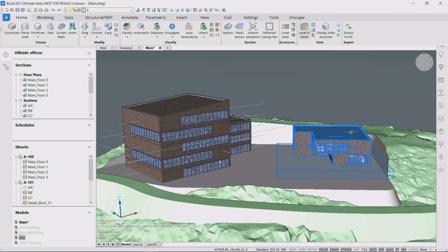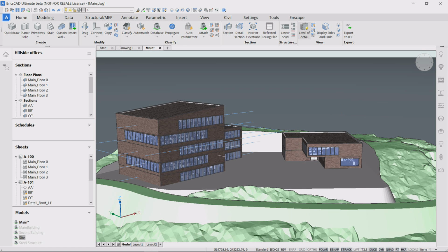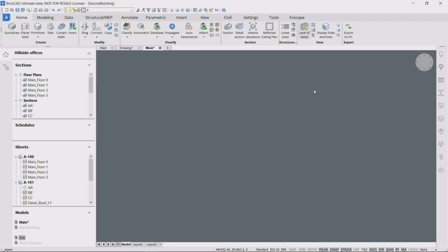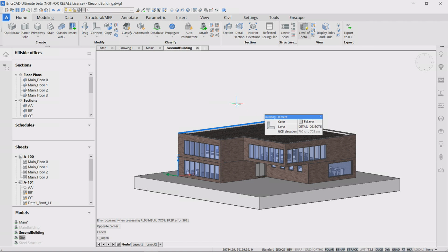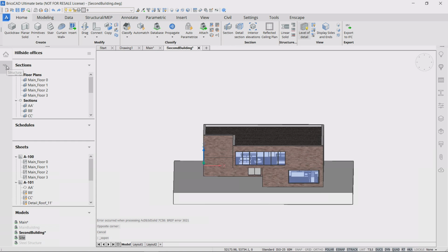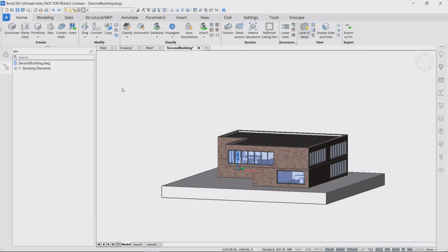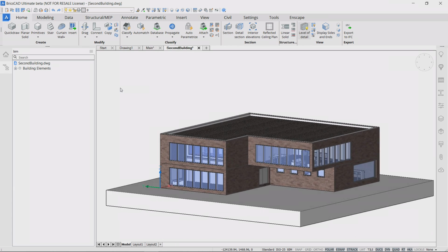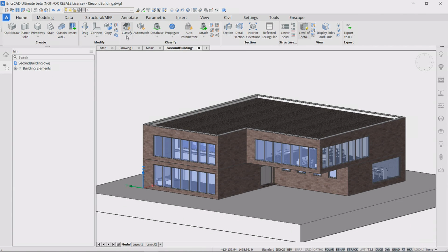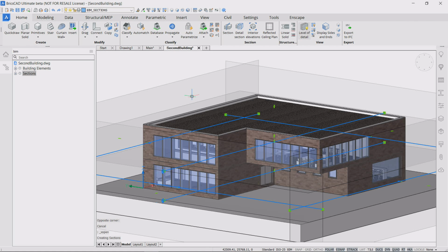You then might wonder, what if I now want to add sections or sheets to my project? Is it still possible? It might seem fixed or something, but nevertheless, it's quite easy to make new sections and add them to your existing project. So we will now make the sections of the second building, because the second building has no sections just yet. So we will run Bimify, just like Jürgen and Wouter did, to make the sections very easily.